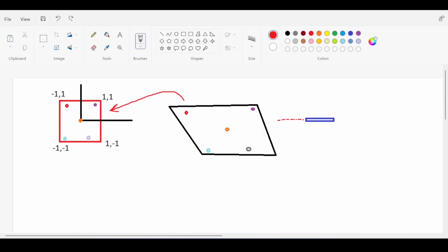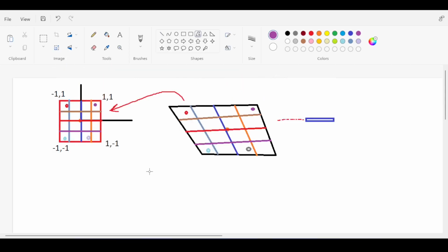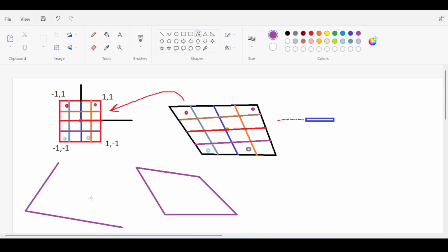Also, there is skewing. And to understand this, here are some helper lines. Allow me to draw helper lines. So you see, the more distortion you have here, the more distortion you get for an isoparametric element. This gets even worse the more distortion you have. For example, take a look at this element. This is one of the worst elements you can get. Like, for example, this, or for example, this. Now, those are still possible, but of course inaccurate.